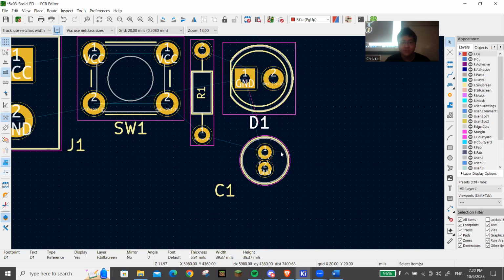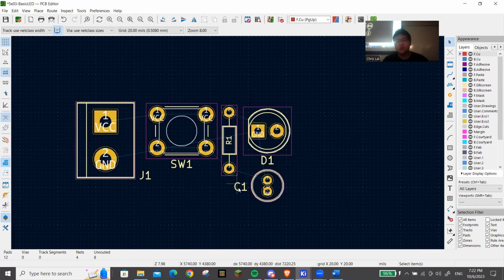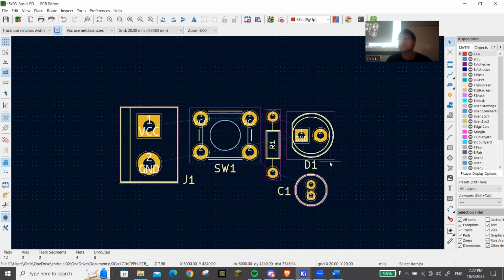Again, what I'm doing is just making the readability of this PCB a lot easier. So when someone is assembling this PCB together, they can go, hey, I know what J1 is. It's a terminal block. I can just put it right there. So what we're going to do next is define the outline of the PCB, right? Like what the shape of the PCB is. And we can do that by clicking on the edge cuts of our PCB here. There's a little item here called edge cuts, and that defines the outer border of the PCB.